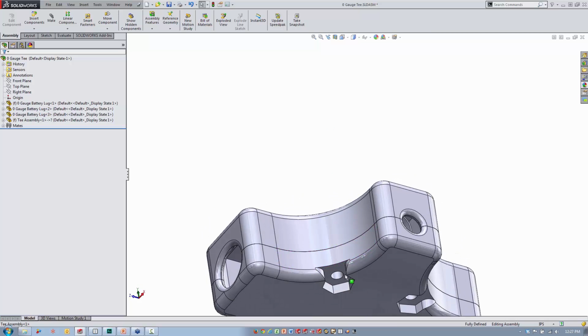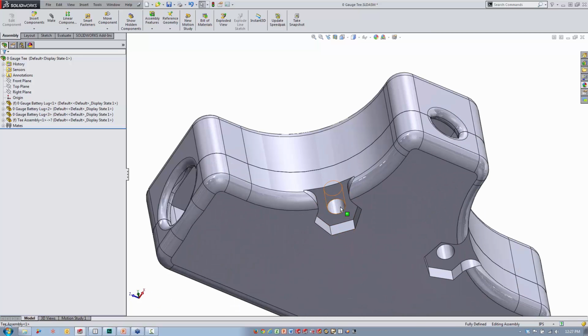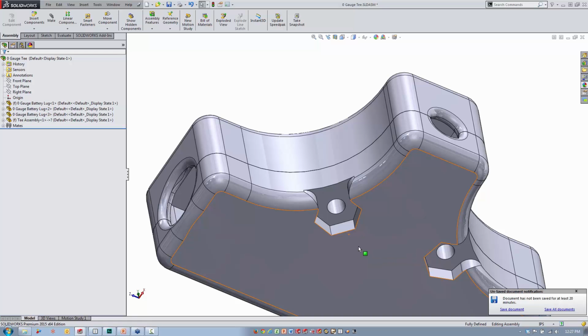One of the neat things that you see a lot in 3D printed parts, when you're involving fasteners, is that instead of doing threads, we do a lot of through holes with nuts and bolts, and we use this sort of hex design to trap the nut. And that means we don't have to use any adhesive in this particular case. It's a nice hidden way of using those nuts and keeping them out of the way.